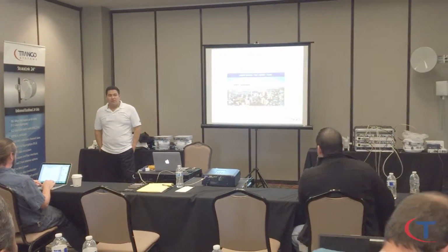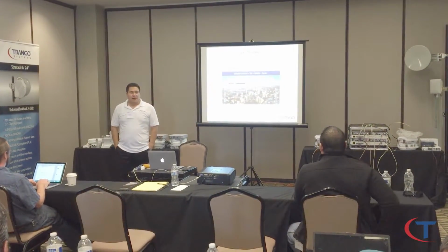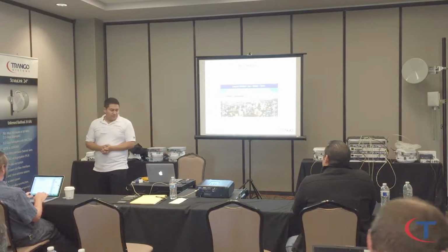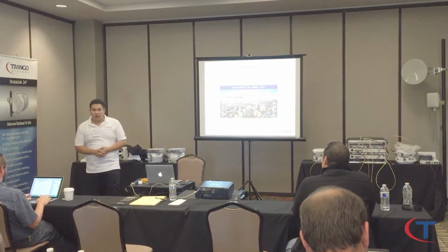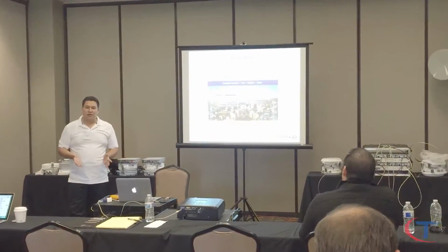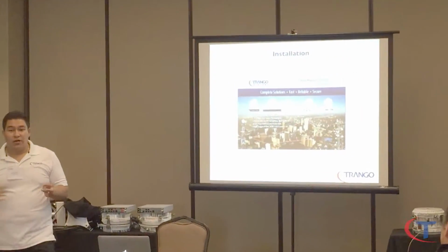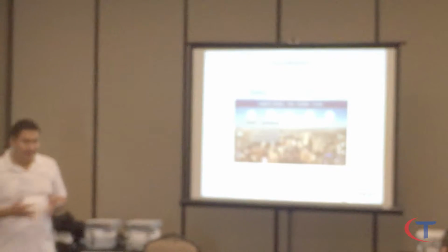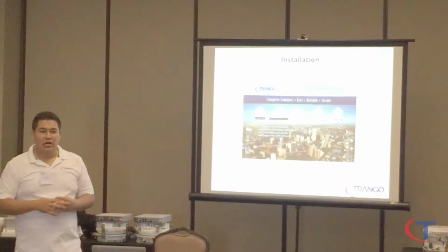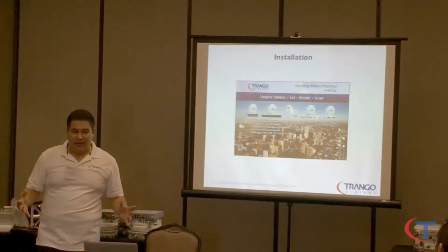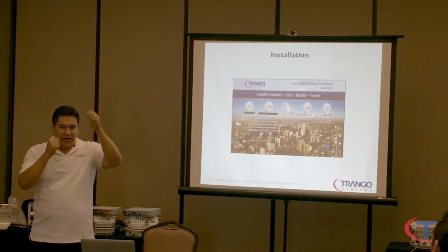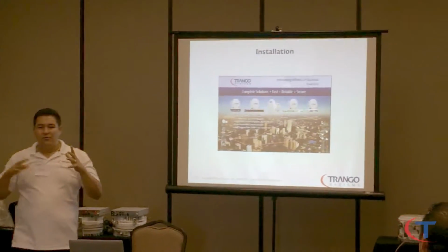So we already covered radio management, interfaces, OBM, IBM, and the antenna alignment process. What is the coarse alignment, fine adjustment? What do I need to take a look for? What do I need to actually align a proper antenna? Now we're going to cover overall installation. What does it take to do the complete install? From the tower side, IF cable, grounding, how it's supposed to look.